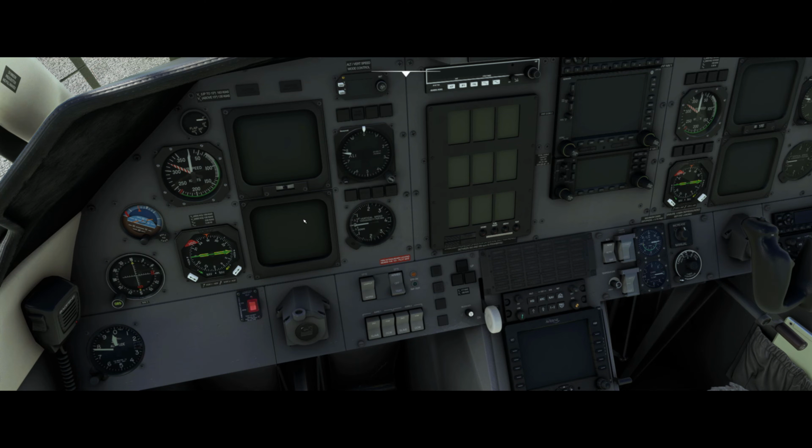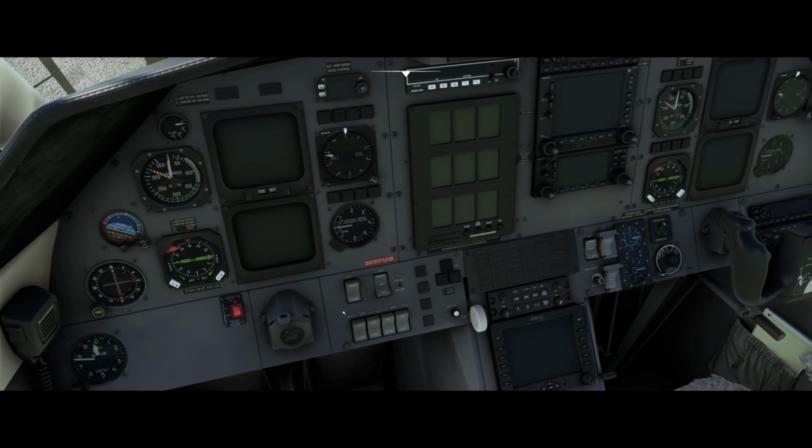So these are CRT displays, they do go bad sometimes. If we lost one of these screens, I could flip this switch to composite and it would pile everything into just one of the displays. So both the attitude indicator and the HSI would be combined into one of those screens. So that should be in norm for normal operations.